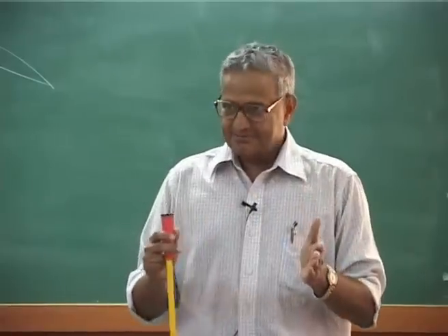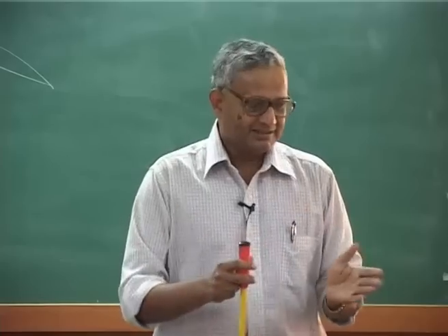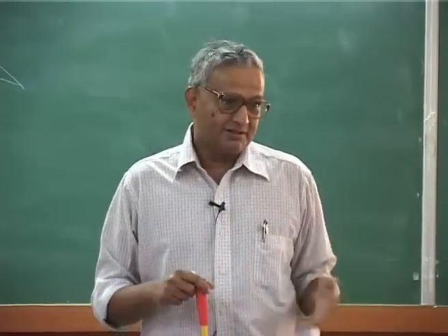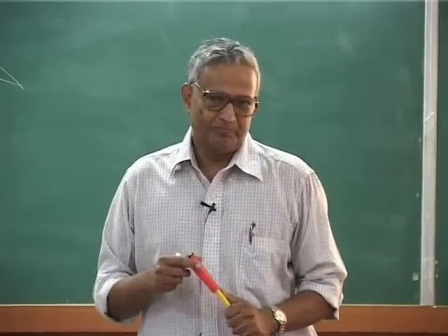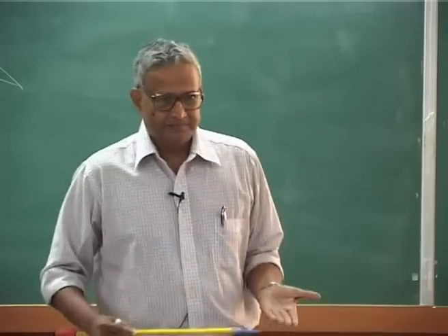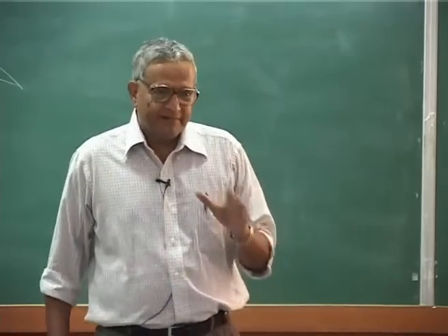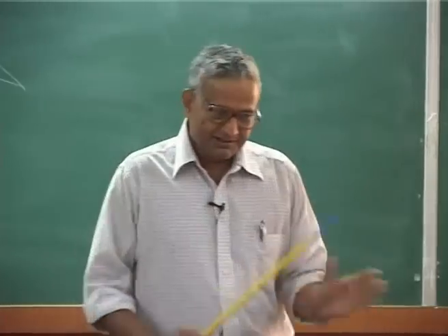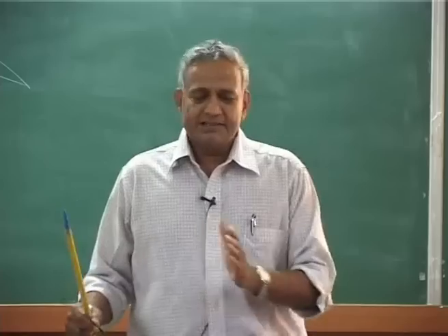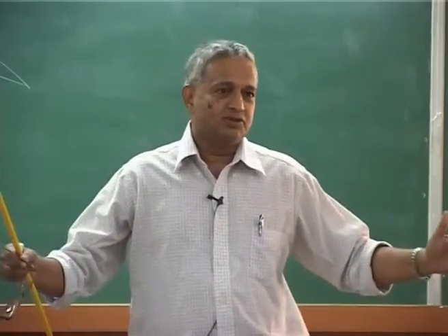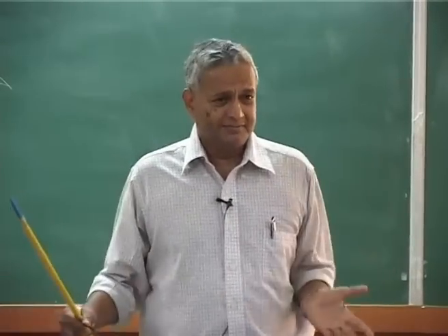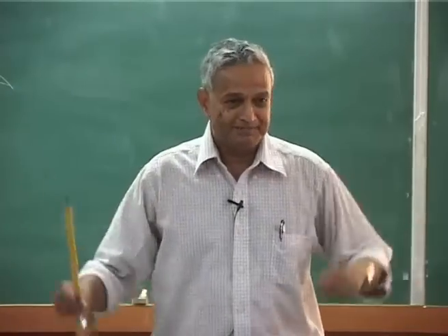When he calculated the thrust, the power, etc., it was not matching with the experiment, because please understand, a lot of propeller experiments were conducted earlier for power and thrust, and he found that they were not matching. He felt there is something wrong between theory and experiment, and he thought the difference is due to the aspect ratio of the propeller, because it is not a long propeller, it is a finite propeller.